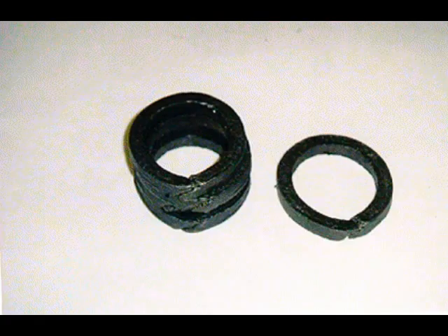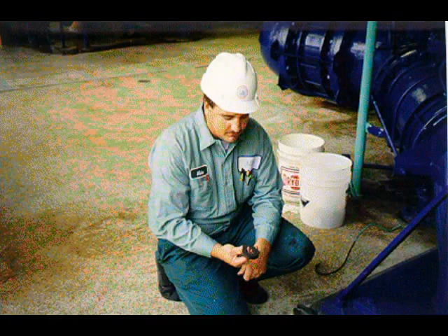It is important that the rings be cut to the correct size. If they are not, service life is reduced. This is where die-formed rings are useful. They give you the exact size ring for the outside of the shaft and the inside of the stuffing box. Also, there is no waste because of incorrectly cut rings.